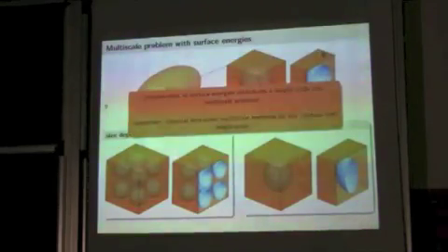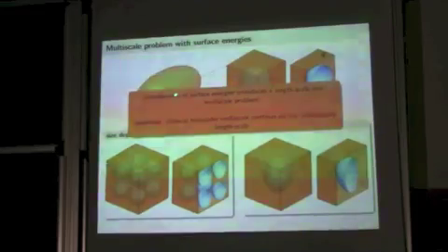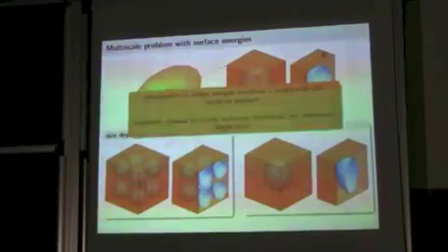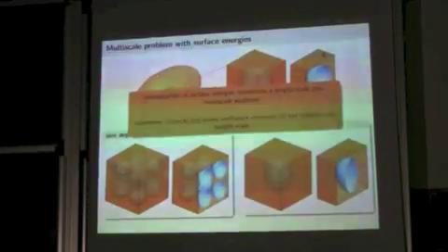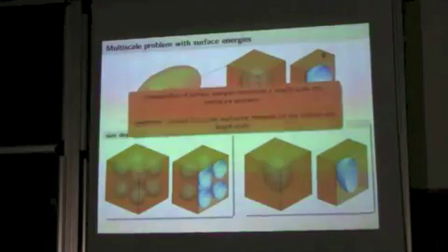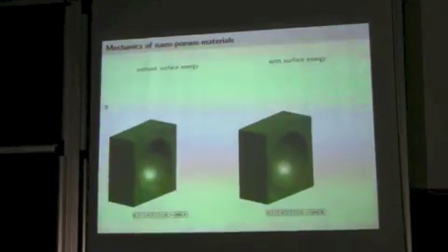So I repeat again that the consideration of surface energy introduces a length scale into multi-scale problems. And please remember that classical first-order multi-scale methods do not contain any length scale. One way to add that additional length scale is to introduce higher gradients, for instance. But this one, again, I repeat, is still a first-order multi-scale method. It has additional surface energy, and it already gives you size effects. So it's a very simple example.